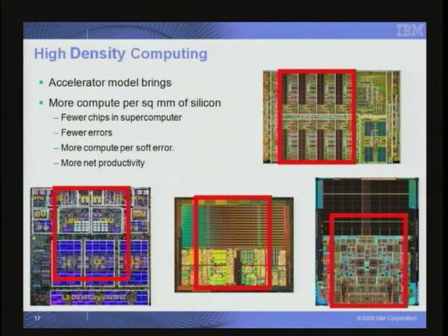The thing that the special purposeness of the SPE is giving us is that we can fit 8 SPUs into the area of a general purpose processor plus its, well, this is a dual core, so two general purpose processors plus the L2 cache that's thought to be required to make that function efficiently. So we're getting more or less a natural factor of 4 in performance per unit area by including SPEs in our design.